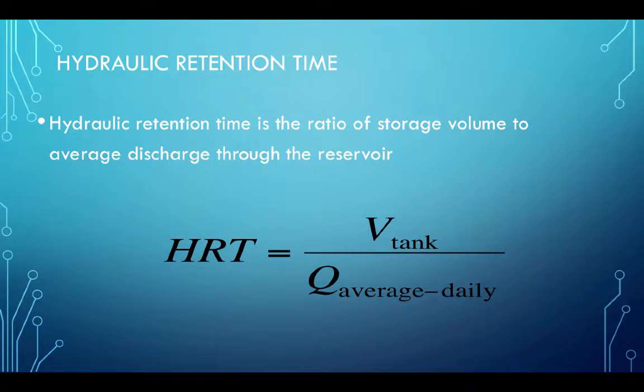The hydraulic retention time, you had that in environmental engineering. That's simply the tank volume divided by the flow rate, has units of time, and it tells on average how many days a water molecule coming into that tank will stay there before it leaves again.